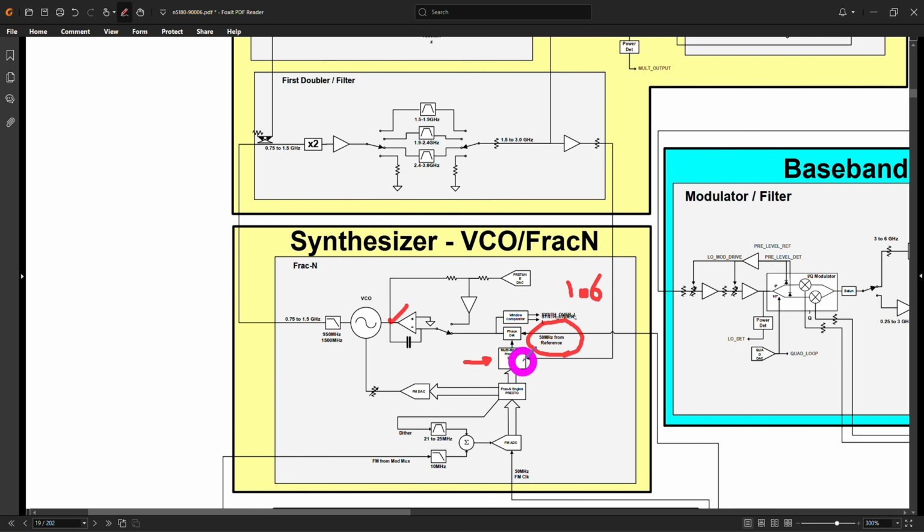So this fractional-N chooses a division ratio such that 1.6 divided by that division ratio becomes 50 megahertz when you're asking for 1.6. So essentially we can force it near its own locking condition and make sure that this guy can divide and produce 50 megahertz. If this guy does produce 50 megahertz and that tone does go up and down by adjusting this frequency ever so slightly, then the divider is also working. Then there's really only one other thing left, which is a phase detector at that point. And of course the circuitry here. So let's try that, see.